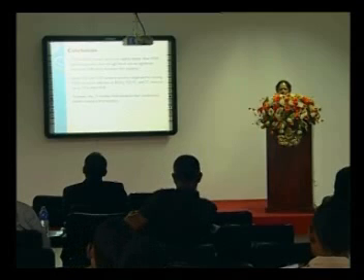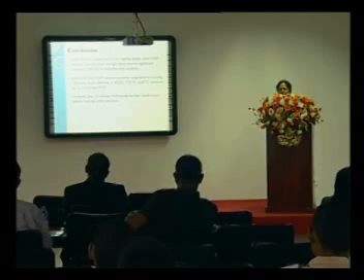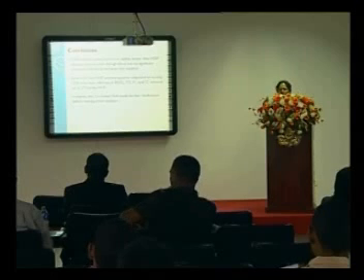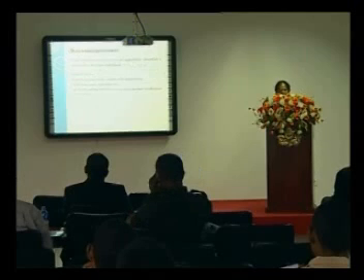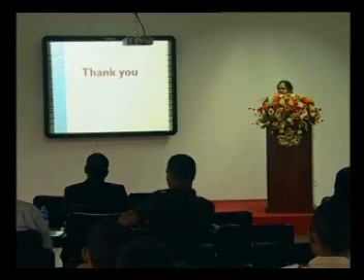Our conclusions were that the vertical subsurface flow wetland system performs slightly better than the horizontal subsurface flow system, even though there is no significant treatment difference between them. Both systems were able to remove pollutants substantially up to 25 centimeters per day hydraulic loading rate. However, this 25 centimeters per day hydraulic loading rate needs further clarification before making a firm decision. Thank you.